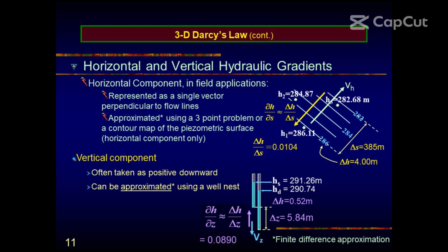But for aquifers, because aquifers mean they conduct, isn't it? It has a reasonable amount of interconnected pores. So the height of the capillary fringe is so small, and more often than not, it is indistinguishable from the phreatic surface. Like when you come here, the phreatic surface will be something imaginary, not physical, like an imaginary line below the water table, taking care of the capillary fringe, because above it is the capillary fringe.